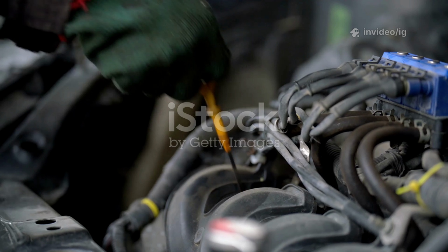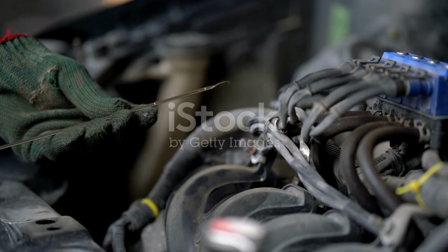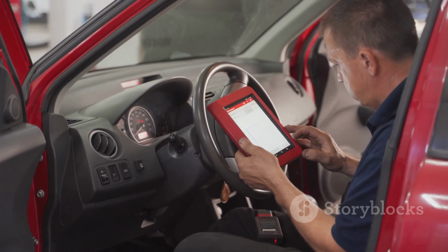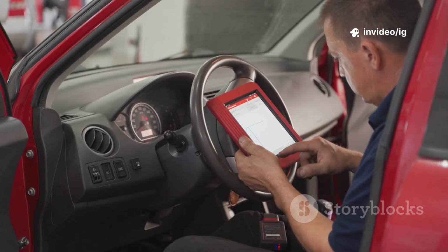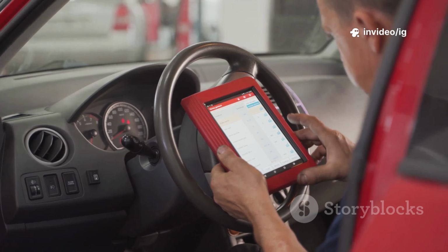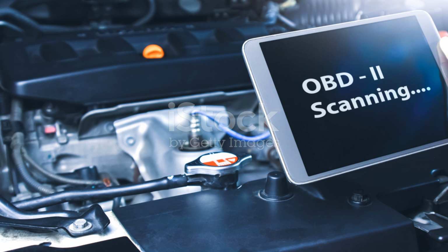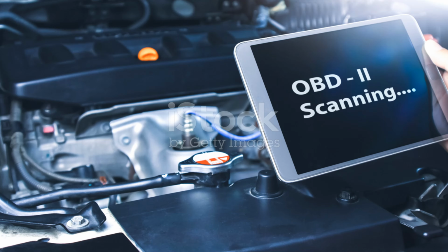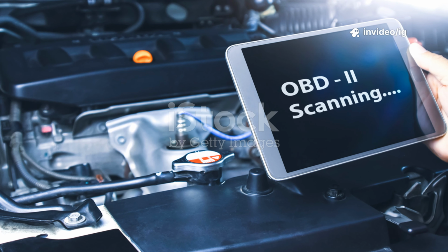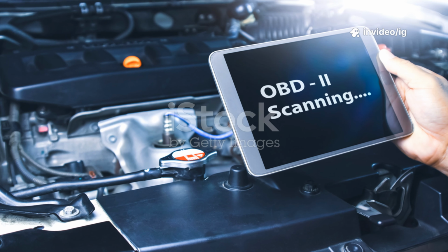Step 3. Examine wiring and connectors. Look for loose connections, broken wires, or corrosion in the circuit. Step 4. Test the transmission control module. A failing TCM may require reprogramming or replacement. Step 5. Check the instrument cluster. If gear changes aren't displayed properly, the issue could be here. Step 6. Reset the code and test drive. Clear the P0815 code and verify the fix with a test drive.